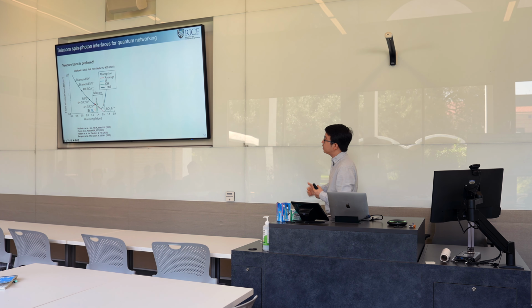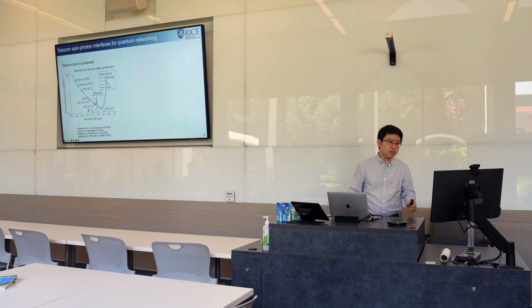So if you're using the fiber, the transmission loss is an issue, right? So here you can see this fiber attenuation at different wavelengths, right? So the loss in the fiber is mostly limited by 3 things. One is the Rayleigh scattering, one is the IR vibrational mode absorption, and then the other one is this OH, which people call the water peak in the glass.